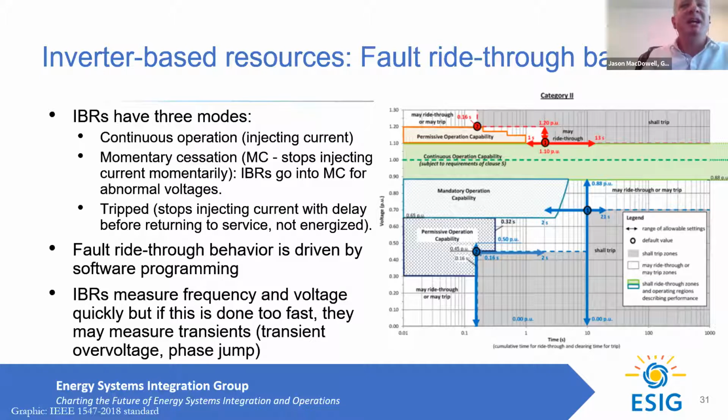So fundamentally, these requirements have happened over time. We have standards like IEEE 1547 that require it, and new standards that I'll talk about in a minute, like IEEE P2800, that fundamentally say, in all cases, resources must remain online, must provide the support of reactive power and support of active power during frequency disturbances to remain online and not trip off during these disturbances.